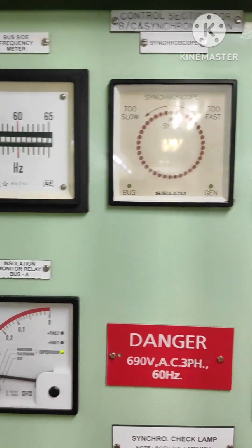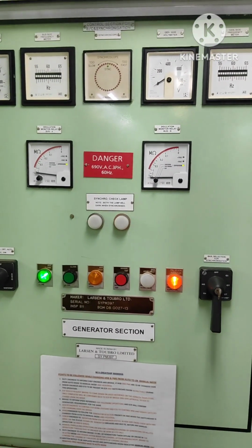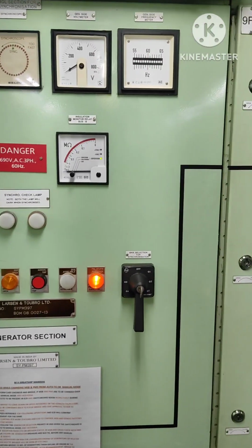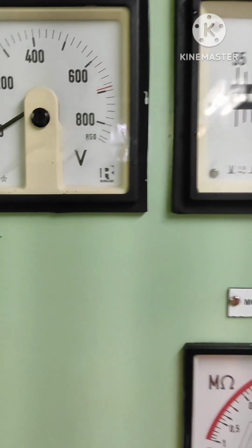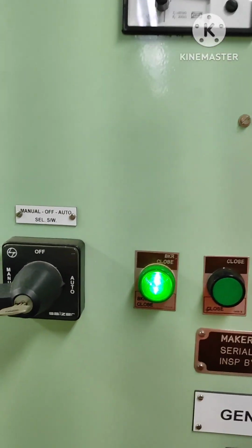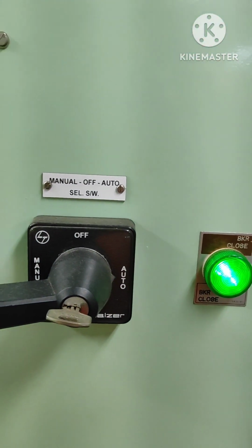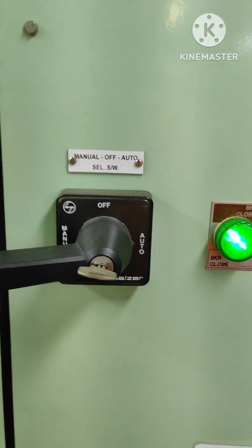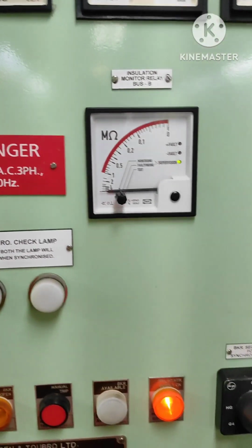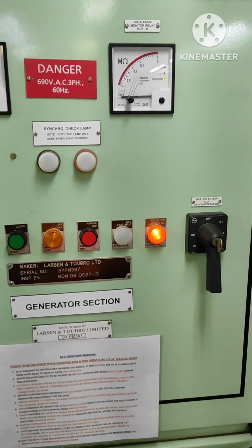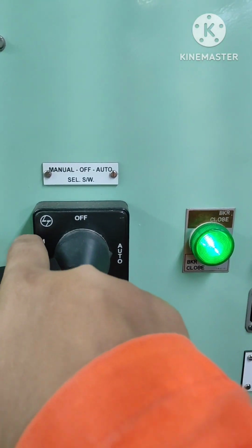So as you all know the basic idea, this panel will be used to connect an incoming alternator with the already running alternator. That means the incoming machine with the connected machine, and that too when the panel is in manual mode. Like here, now it is on auto mode, so no need to do anything here. We have got PMS. Through PMS, when we start one engine, the alternator will start, the voltage will be developed, and all the required conditions will be matched, fulfilled, and then the breaker is closed. In case there is trouble with the auto, we'll have to shift this to the manual mode.